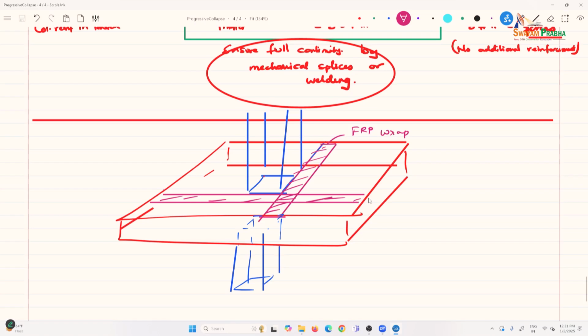I'd look into what they do in enhancing the shear strength of materials, and use very similar principles. These FRP wraps work very well in tension. Even in columns, you could consider wrapping the entire column with FRP wraps, FRP sheets basically. Anybody's got experience in that?